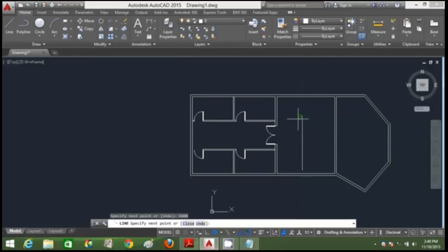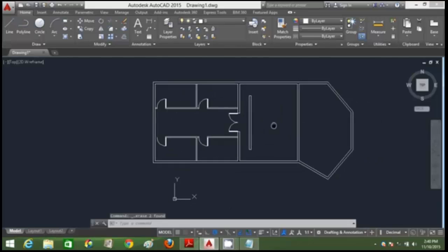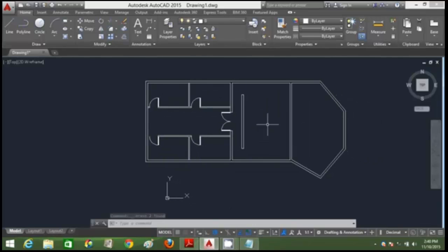So now I'm gonna draw the backdrop wall for the reception, using the dimensions stated on the floor plan layout. I'm just gonna draw it first, then move it later to centralize it. I'm drawing my reference lines first by 1000 mm and move the backdrop wall there. After that I can delete all the reference lines. Alright, I've created the backdrop wall.